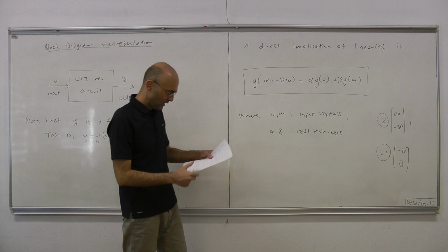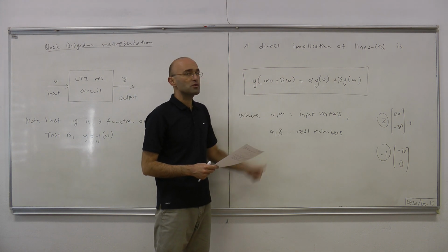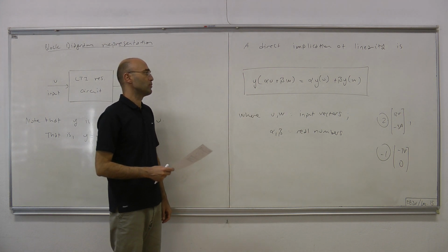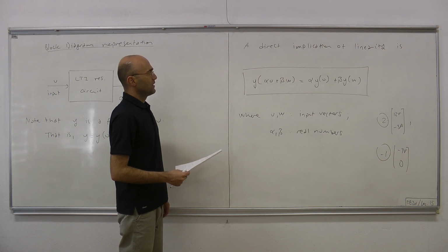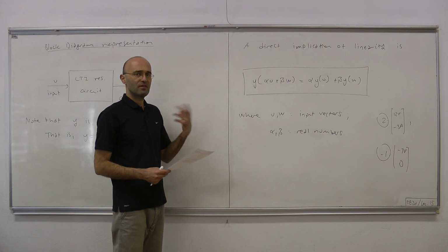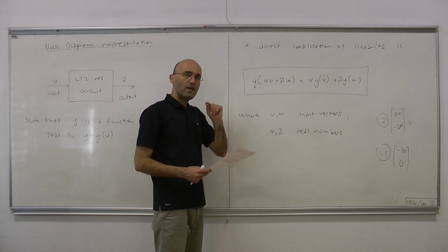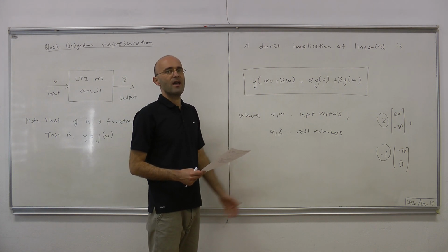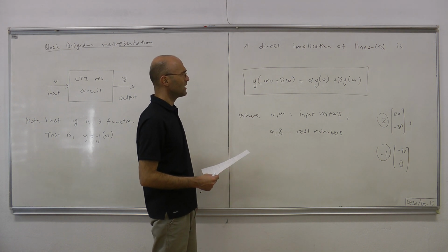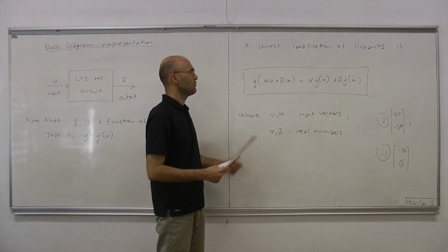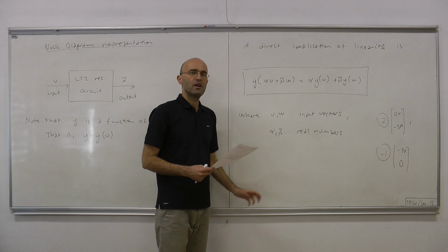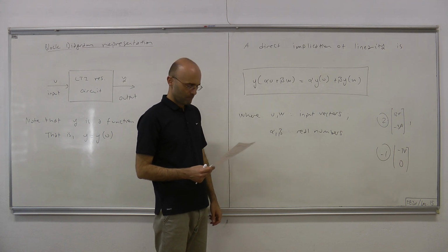Now we will make use of this very nice property in superposition. That property will allow us to consider one input at a time, and then we combine our findings to figure out the overall output when all the sources are active.